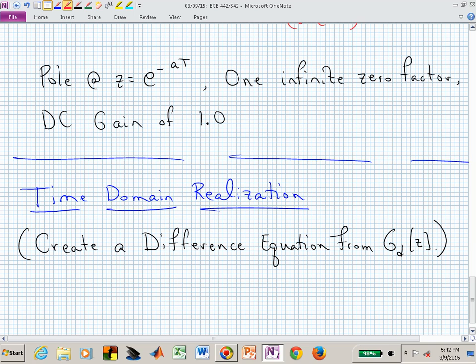You can now do this difference equation in order to low pass filter the signal that you're given, this string of numbers. You are taking this string of numbers, we'll call it e's, and produce an output sequence that's now the low pass filtered version of that input sequence.